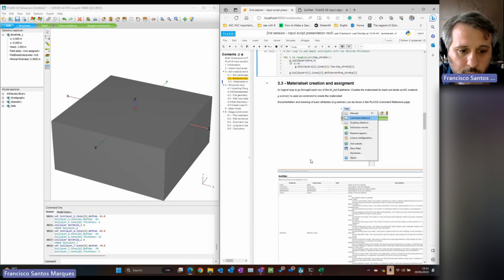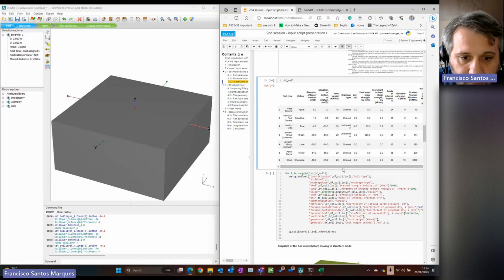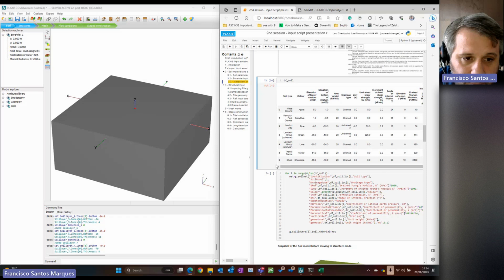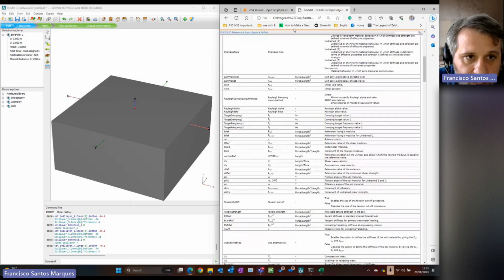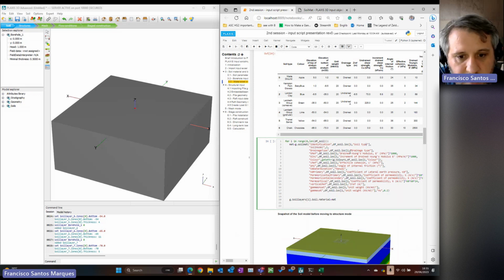Okay. So the whole idea is that now that we have this, if I go back here to the data frame with the soil properties, we have the properties here. Now what we want is to iterate each row, and for each row, this function, soilmat, is already specified for the right parameters. So you have to go to the documentation and see which parameters you want to assign, and then you just put the property and the value, then property, value, and so on. That's how it's sorted out.